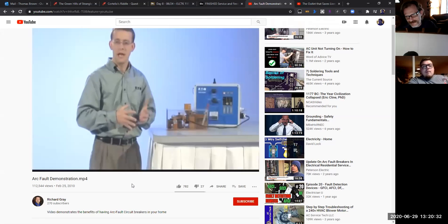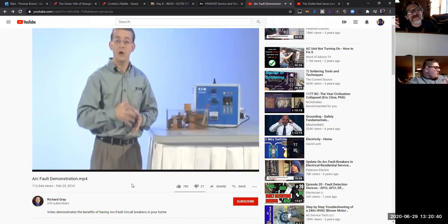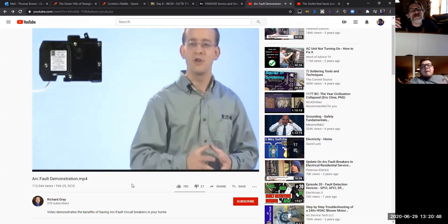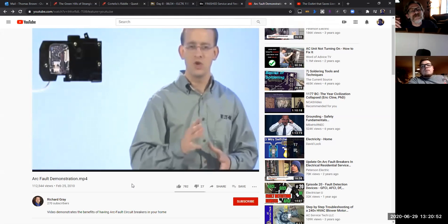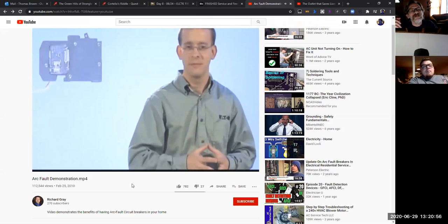The branch feeder AFCI was launched around 1994 to provide the overload and short circuit protection, plus protection for the high current arcing where the current exceeds 2 to 3 times the breaker's rating. Internal to the AFCI, a current monitoring circuit board detects any anomalies in the current flow and trips the breaker when a current signature matching an arc is detected.